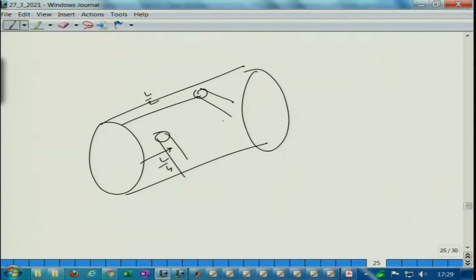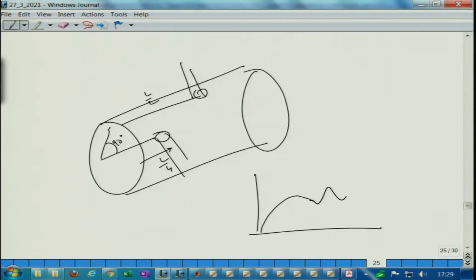This is something like this and this is like this. So, the included angle between this is 90 degrees, then you would get a broadband attenuation. You have multiple peaks and you will get a broadband attenuation. First, second, third resonance troughs are basically eliminated, and with 90 degrees you can also get rid of the 1-0 mode, but the 2-0 mode you are going to have problems, at that point the attenuation is going to fail.